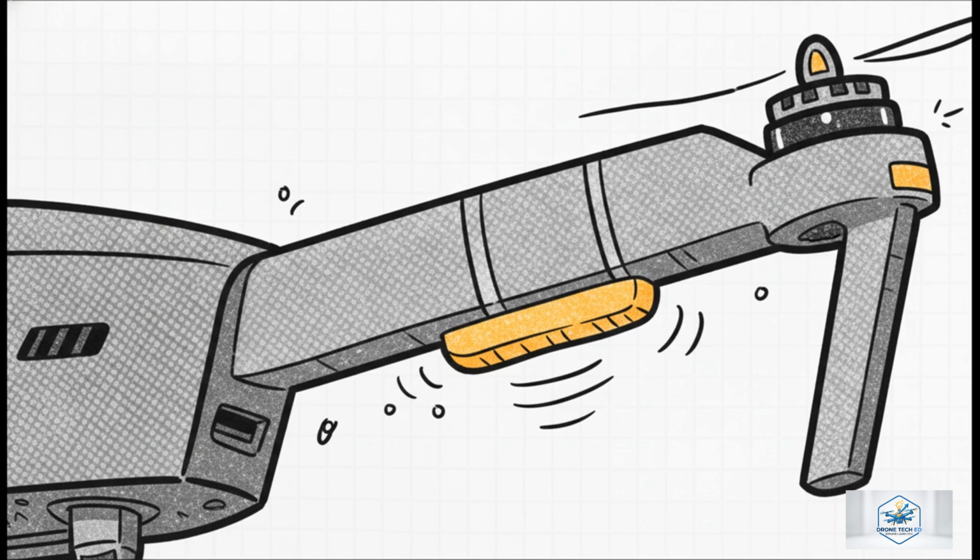Carbon fiber is super stiff, meaning it transmits vibration like crazy. That's why we integrate TPU inserts. Think of them as shock-absorbing sneaker soles for your drone. These viscoelastic dampeners absorb acoustic vibrations before they can rattle the drone's ultra-sensitive internal sensors.